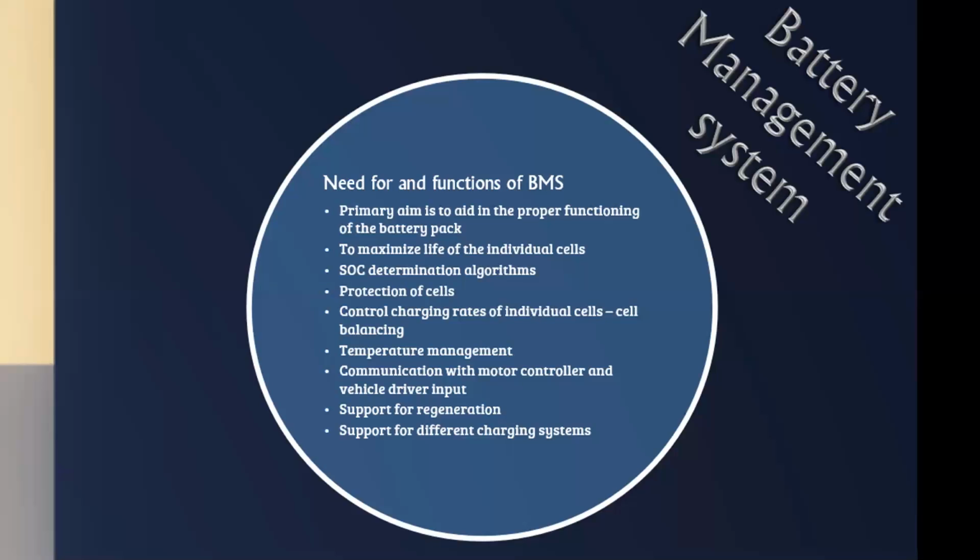So we see that not all battery management systems are the same. Based on the selection criteria, it differs on what you exactly need from the battery management system. If you are also including regeneration, then you would have to consider a battery management system that supports bidirectional power. So all these functions are handled by your BMS.